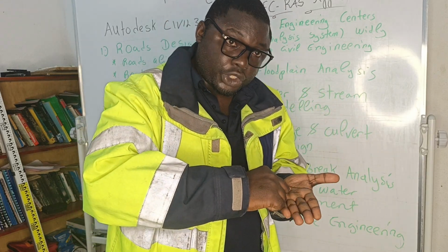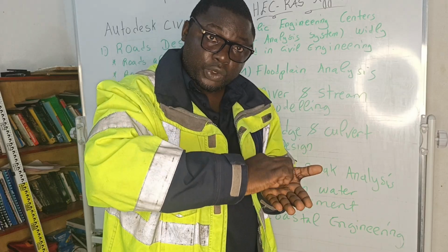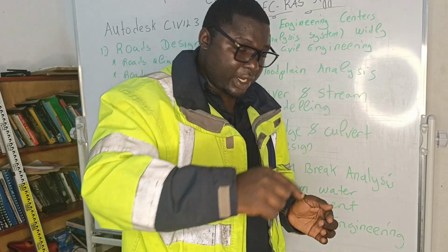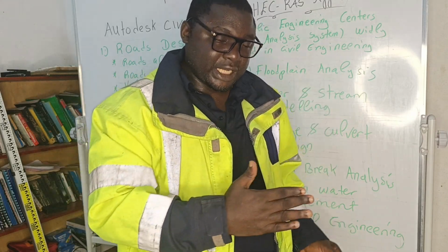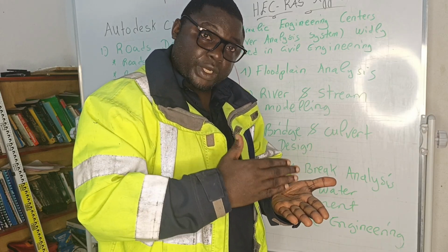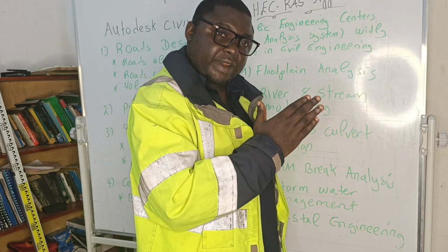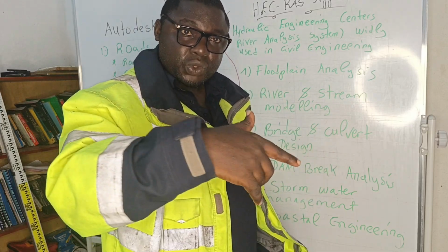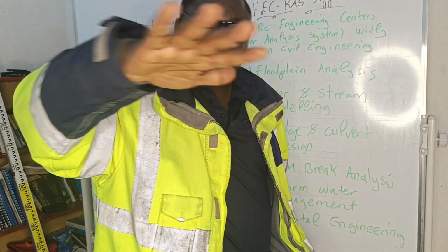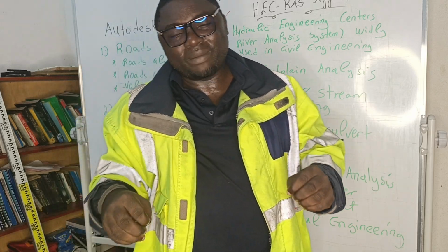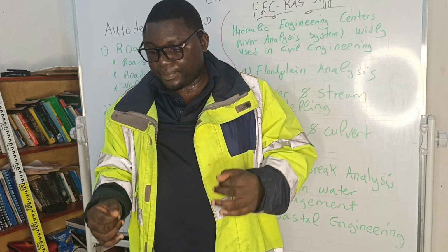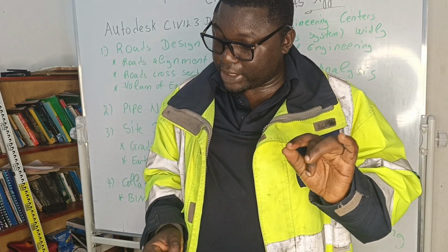So we're going to deal with a longitudinal section of a road from, let's say, Akure to Ife. Of course, remember that road also has the lateral, what they call east-west. On a road project, what they usually do is take sections of the road east-west, let's say at an interval of 20 meters. So let's say you are leaving Port Harcourt to a nearby city. Every 20 meters, we cut the road to see how the road behaves. You understand? All these elements we use to do what they call estimation of volume of earthworks. We are going to get into the details of that.